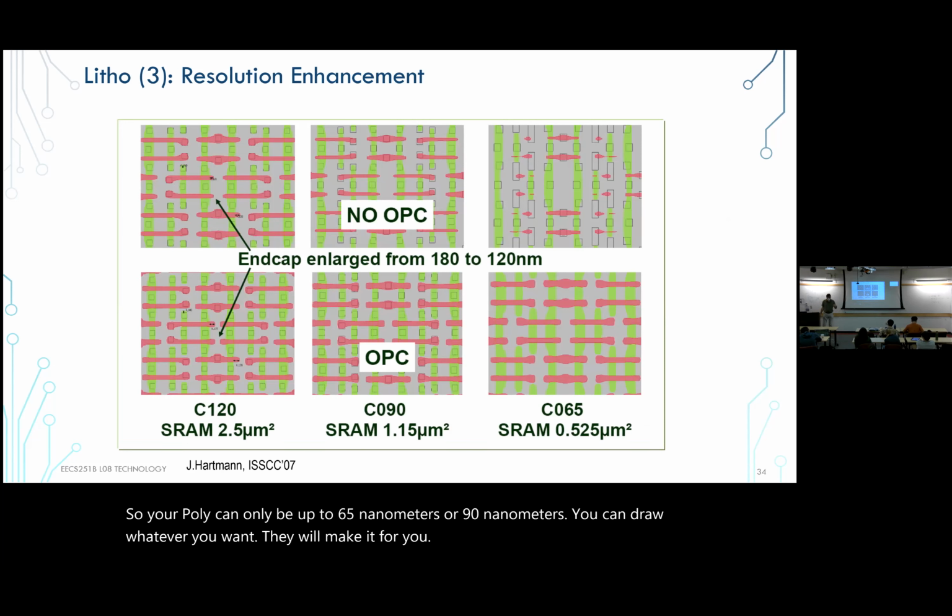No such thing anymore. Your poly has to be vertical. Your pins have to be horizontal, and no discussion about that. You get the DRC error if you try to do anything else.